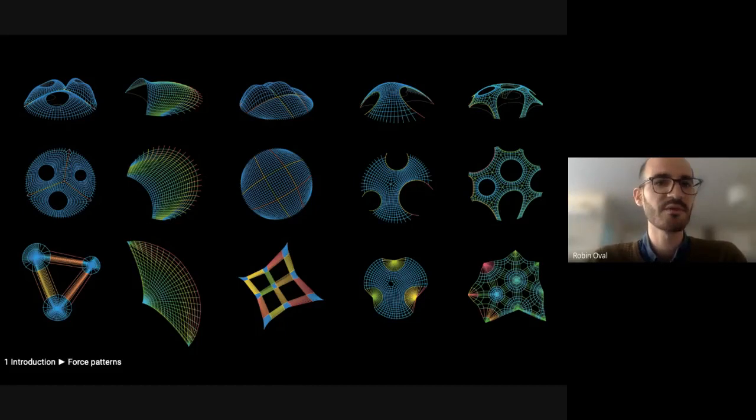And here the presented approach, thrust network analysis, actually relies on graphic statics. So you have a form diagram in the center that shows the layout of the forces in your structure, and the reciprocal diagram at the bottom that will give the magnitude of forces to be in compression-only equilibrium and get a funicular design like this.